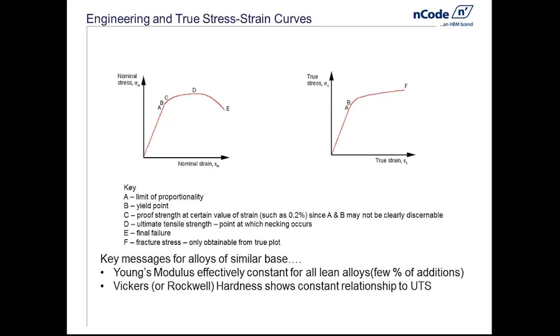It's particularly true in most metals such as aluminium, and therefore to provide consistency between the different laboratories' measures, you will take a proof strength at a certain value of strain, such as 0.2%, as I say on there. The other figure on there is one that we live by, which is the ultimate tensile strength, which in engineering terms is the maximum stress it'll experience in engineering terms.